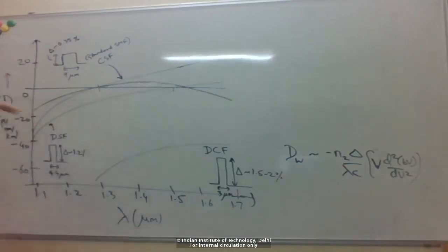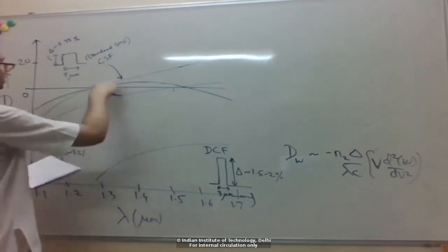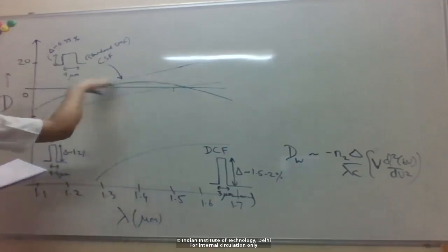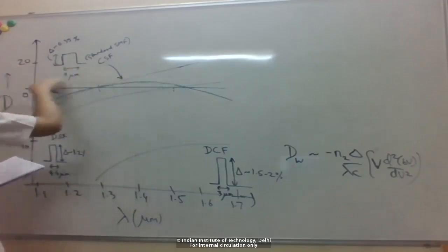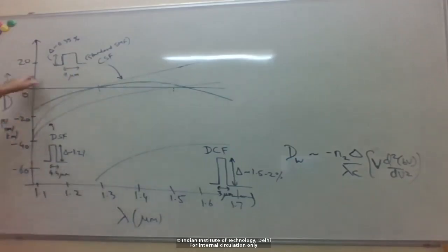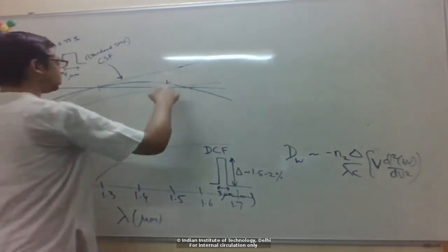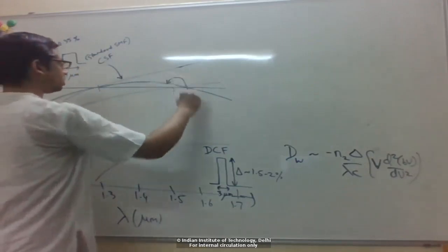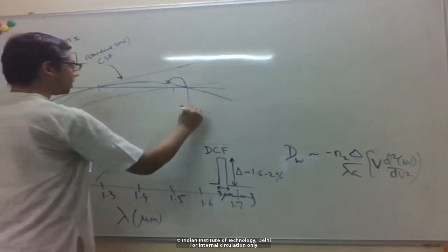Okay. So over this telecom wavelength range, the dispersion is sort of flat, doesn't change much, and it's also very low. Okay. So typically maybe 5 picosecond per nanometer per kilometer. So these are known as dispersion flattened fiber.